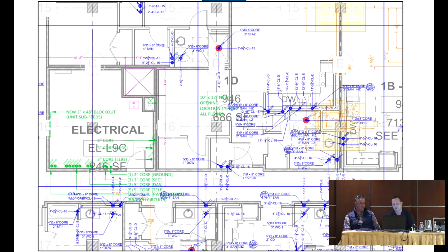So green would be electrical, blue is the plumber, magenta, we don't have too much here, is the duct risers, and then red would be sprinkler, but in this case, some of these other cores are kind of unique, so they're also isolated as such. Orange is the existing. And you'll see each one of these cores has a unique identifying number. So for every single core on this project, we know where it is, its location in XYZ, diameter, thickness of the slab, and all that sort of information, as well as how it relates to what is in that slab for that specific core.